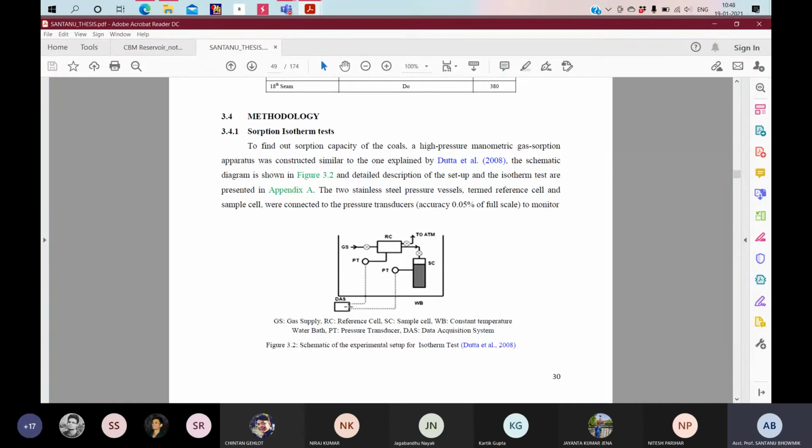So per second you can take the variation of the pressure. This total thing, not the computer, not the data monitoring system, but the pressure transducer, the valve, the total setup. Obviously you have to keep some pipeline which you are venting out to the atmosphere, otherwise water will be coming into that. This total thing is immersed into the water or the oil, a fixed temperature oil bath.